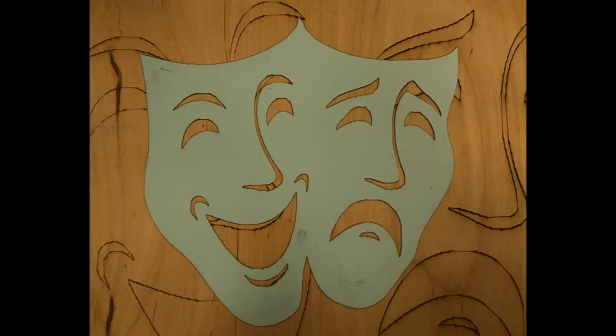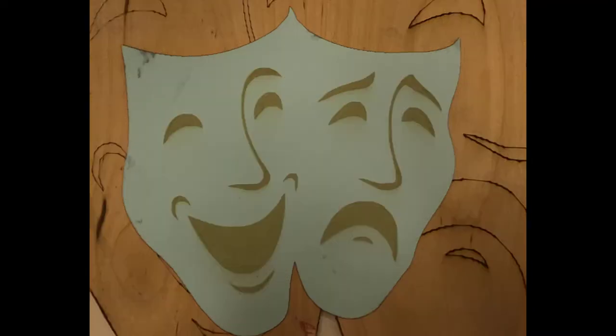One of the things worthy of playing with is looking at cutting versus scanning. If I cut something, it's going to cut all the way through the paper. If I scan, it's going to etch. So I like to use cardboard paper as an experiment because it's cheap, and I can go in and say, let's scan, which takes a lot longer because it's rasterizing, and generate an etched image on top of a piece of paper.